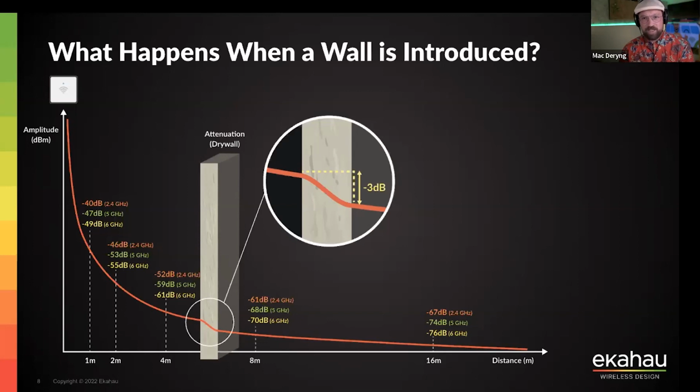So now the free space path loss and attenuation of walls and attenuation areas, it's exactly what Ekahau is using by default to calculate how the radio waves will propagate away from a radio. So we know the propagation pattern of an antenna or an AP, and then we use free space path loss plus attenuation to calculate it all. On top of it, now with the addition of AI Pro, we've added also diffractions and reflections to make it even more accurate when it comes to modeling of how Wi-Fi signal propagates.